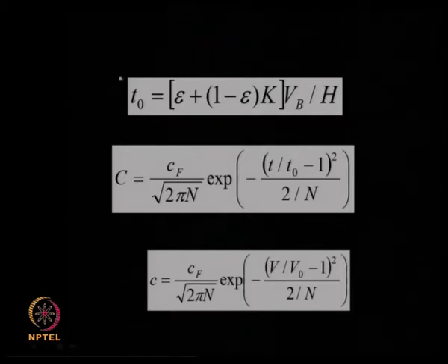And then T naught, that is the elution time, that is the time at which the peak is maximum, is related to your voidage, it is related to your linear adsorption isotherm term K, volume of the bed and height of the bed, in this fashion.